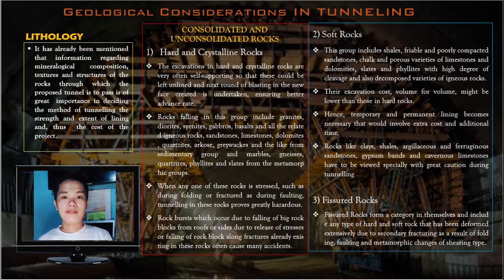Geological considerations in tunneling. Lithology. It has already been mentioned that information regarding mineralogical composition, textures, and structures of the rocks through which the proposed tunnel is to pass is of great importance in deciding the method of tunneling, the strength and extent of lining, and thus the cost of the project.